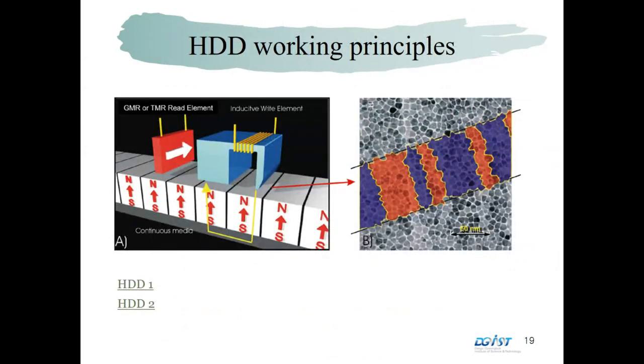And in a hard disk drive, we have a read head, which reads the stray field from the surface of the hard disk. If we have a sensitive sensor, we can make a smaller bit, which means we can increase the density of the recorded information. So a better magnetic field sensor means you can make a better hard disk drive, or increase its capacity.